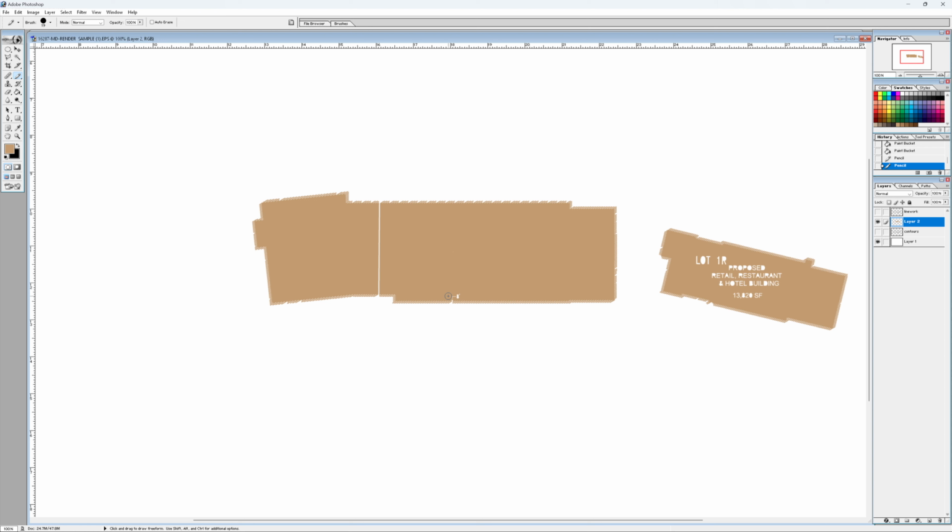I might do that, or there's a selection tool that I use that you can just kind of outline and hit a couple keys and it fills it in with the paint bucket. And again, you're done. So there's different ways, like I said. But yes, you could take a little bit more time in AutoCAD to clean up all of your text and get that all cleared out so you only have line work.